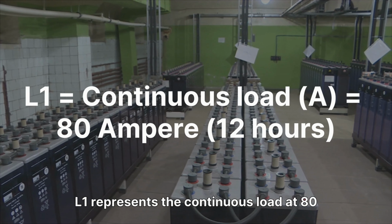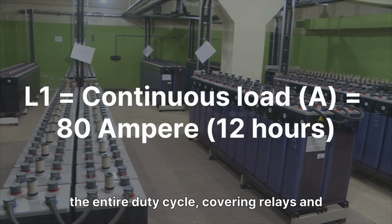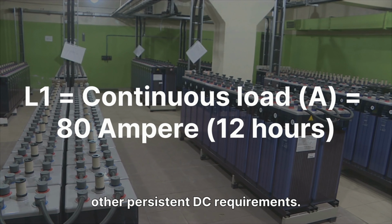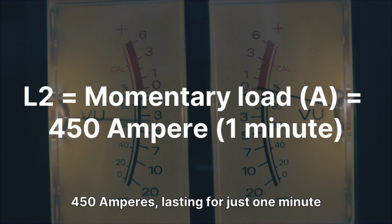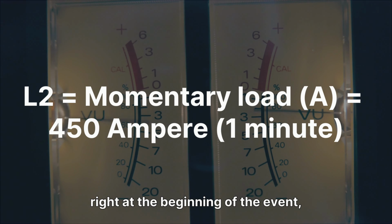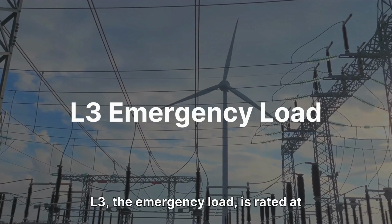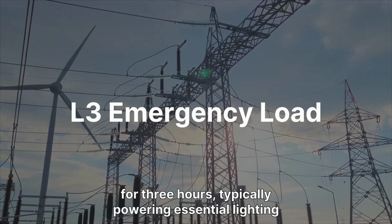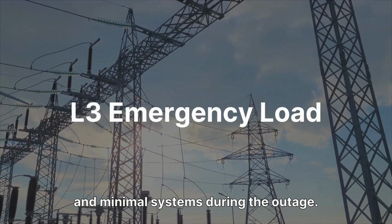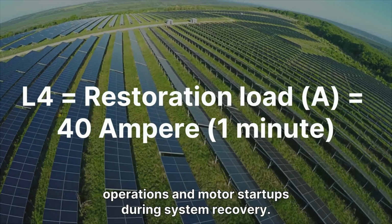L1 represents the continuous load at 80 amperes, which must be sustained by the battery for a full 12 hours throughout the entire duty cycle, covering relays and other persistent DC requirements. L2 is the momentary load peaking at 450 amperes, lasting for just 1 minute right at the beginning of the event, capturing the high inrush from initial tripping sequences. L3, the emergency load, is rated at 10 amperes and is required to last for 3 hours, typically powering essential lighting and minimal systems during the outage. L4, the restoration load, stands at 40 amperes and applies for 1 minute at the very end, accounting for the closing operations and motor startups during system recovery.